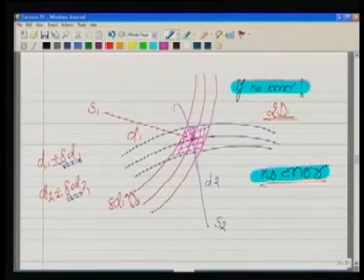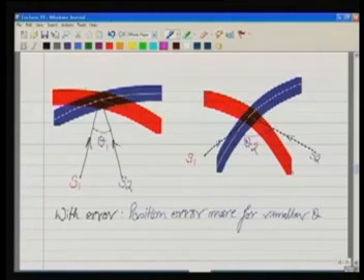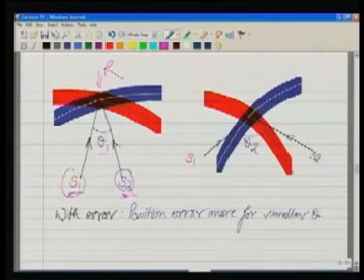Now, let us talk about the geometry, how this is being affected by the geometry. Geometry means the angle between satellites with respect to the receiver. How is it being affected? For that, if the angle is very small between two satellites at the receiver, this is the case; the blue one is for satellite S2 and the red is the envelope of uncertainty for S1. Similarly here, if the angle is around 90 degrees, this is the case.